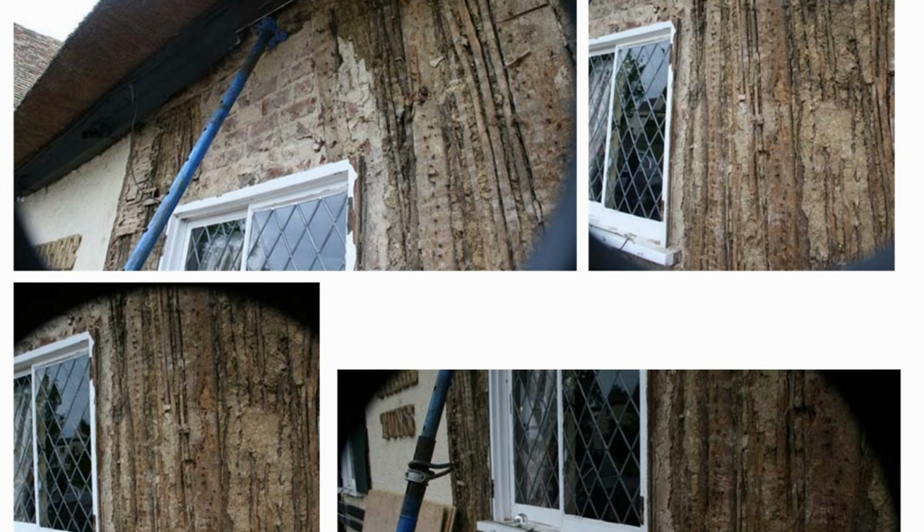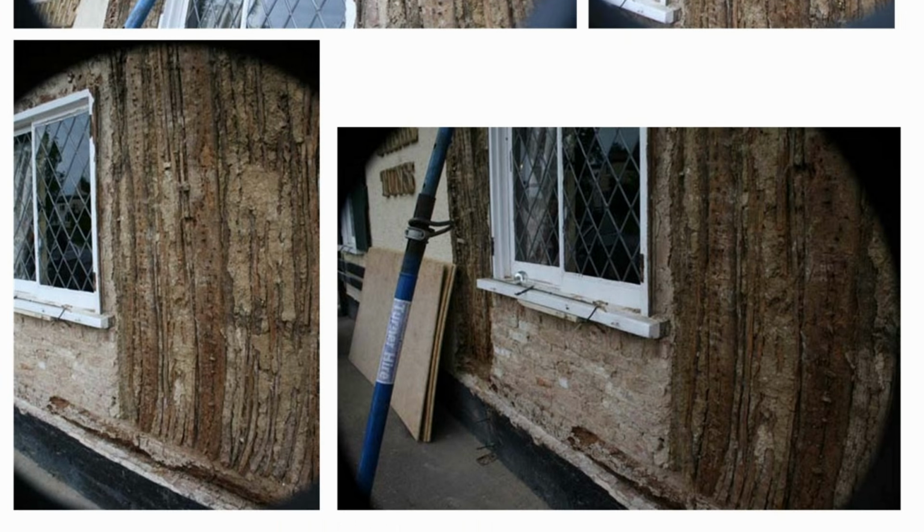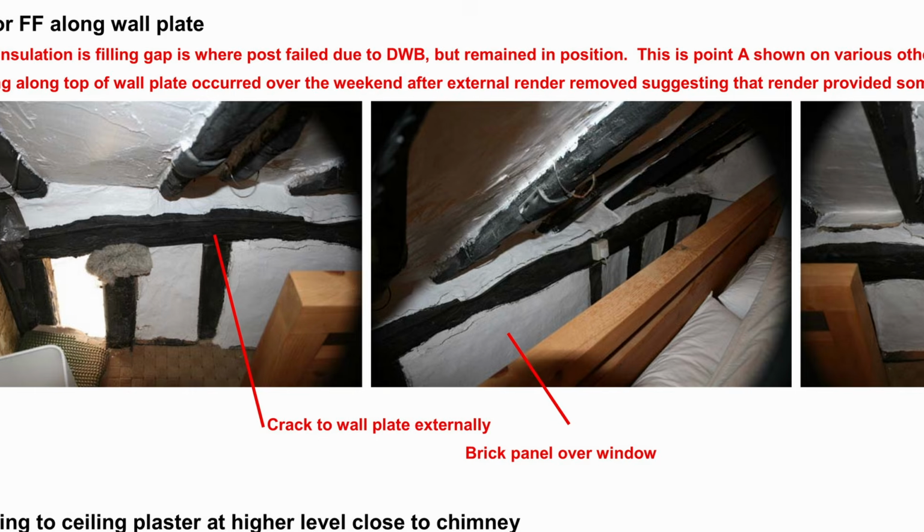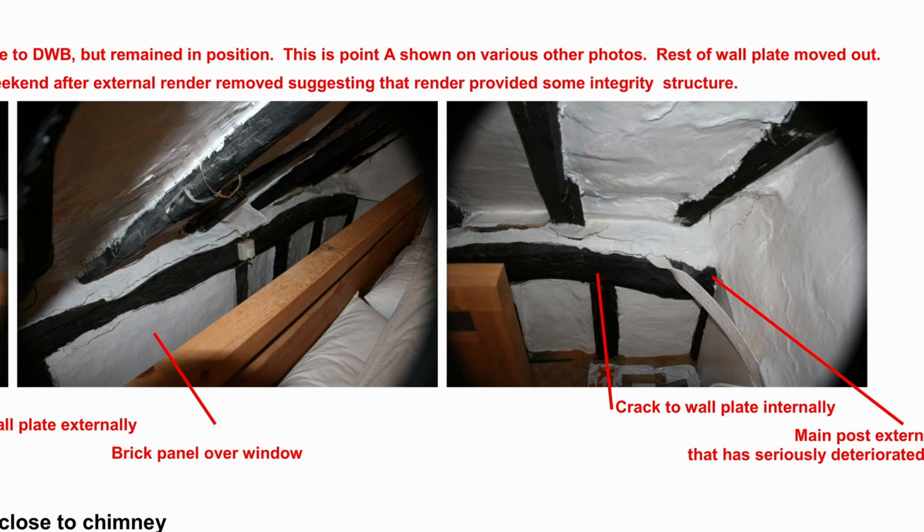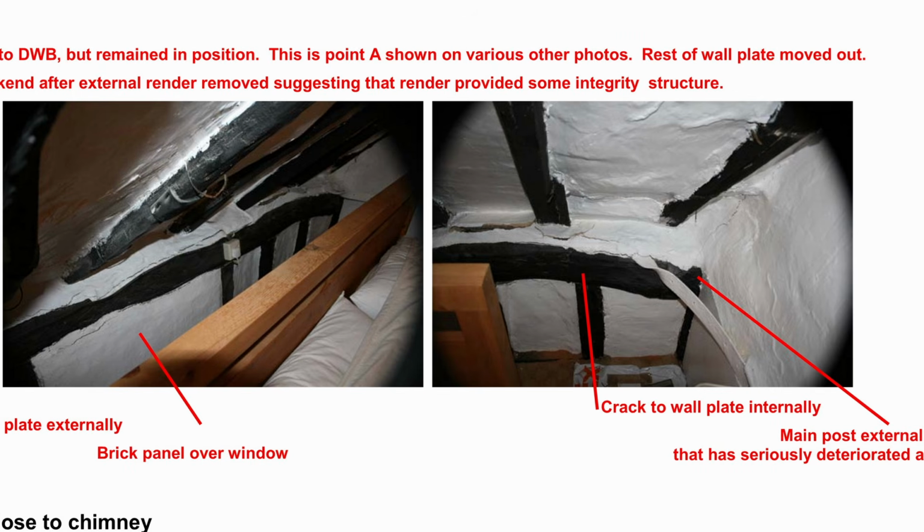What you've got to try and differentiate between is that crack due to a more general structural movement, or is it because there's a timber somewhere nearby that has failed, that's starting to crush out because it can't take the load? So the masonry or whatever is above it has started to drop, and therefore you've got a crack. So it's looking for these defects that could indicate a timber that is deteriorating and has lost its capacity to bear load.